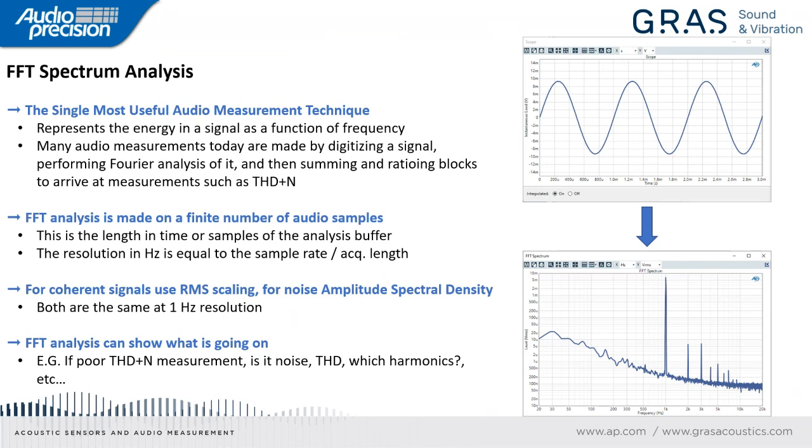And the frequency resolution is important just because we won't be able to suss out features that are in the same FFT bin. So let's say our frequency resolution is so low that two signals that we're interested in just show up in the same bin. We won't be able to suss them out.